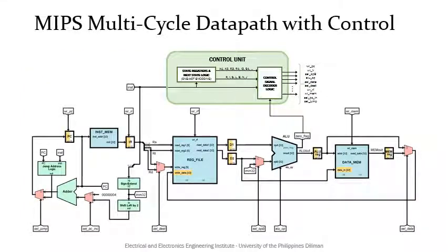Our multi-cycle processor with the data path and control unit must look like this. The instruction store.ir is fed to the control unit along with the zero flag. Within the control unit are the state registers, the next state logic, and the output logic to complete the FSM. Aside from the state signals A1, A2, R3, R4, etc., the instruction identifier signals are also generated based on the opcode. With this setup, the control unit is able to generate the control signals that change with the clock cycle.